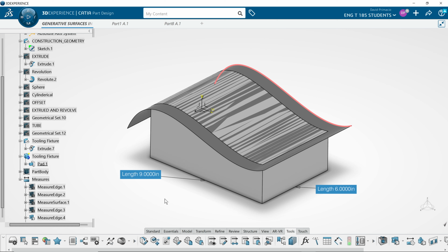So let's say this is a door. We took the engineering surface that represented the door, and we would cut it to a block of aluminum or whatever, some type of block to form that same shape. And we would vacuum suction the part down or clamp the part down so that we can machine it. So in this example, this would be more like an NC mill fixture. We have vacuum lines holding this part in place.